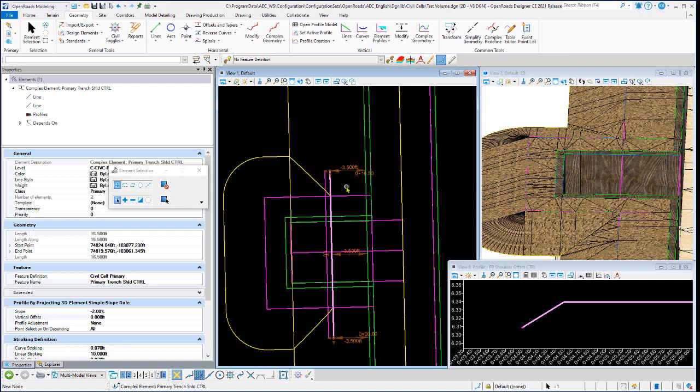One of the first edits you probably should make, and I hate that it's this late in the video, is to align this with the template, the width of your primary trench shoulder. Also notice that -2% slope; you'd want to make that the same slope as this primary trench slope. It's called primary trench shoulder control, and that is that point right there.